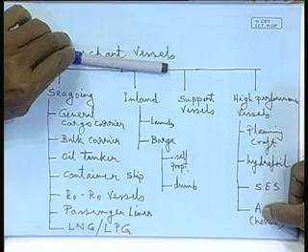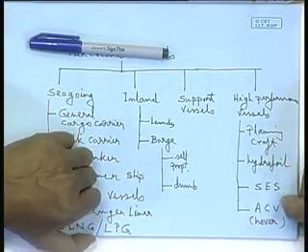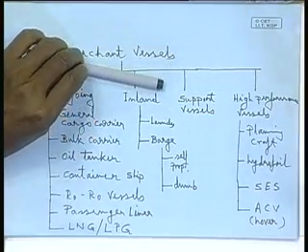The aircraft does not float in water, it is supported by a lift force in air, not by buoyancy. Same thing in planing craft, hydrofoils, SES or ACVs: some kind of lift force, upward thrust, is generated in the hull, so the weight of the vessel is fully or partly supported by that lift force, and the rest by buoyancy. That is why they are called high performance vessels.